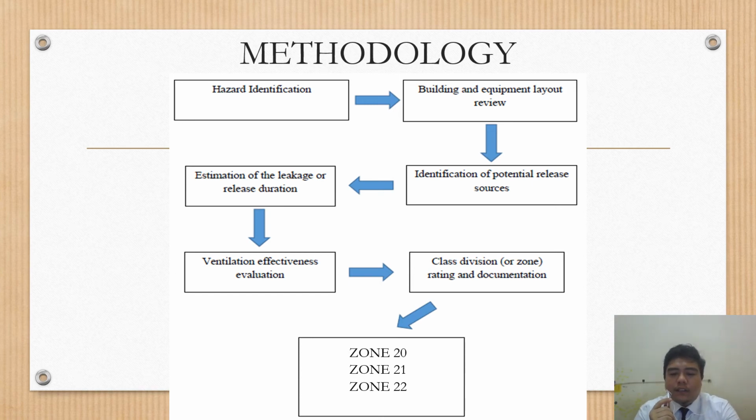Consideration should be given to the fact that fine dust can be carried from a source of release by air movement within a building. Where the classification gives rise to a small unclassified area between classified areas, the classification should be extended to the full area.